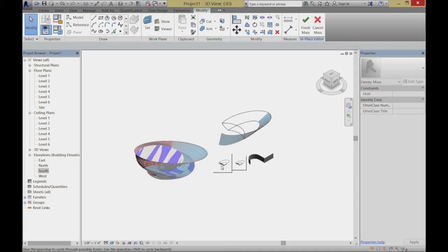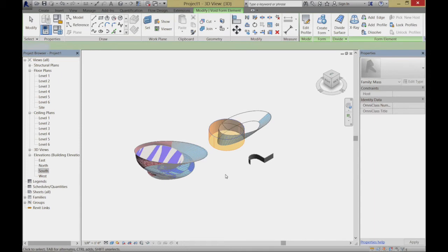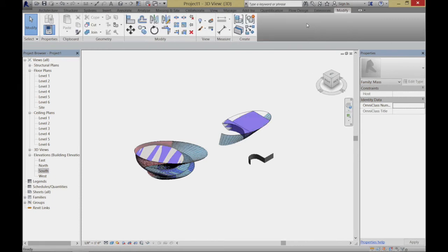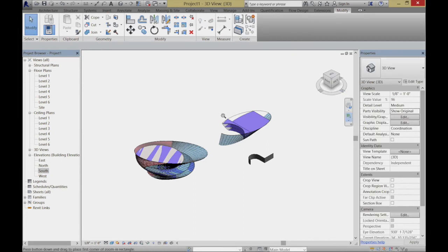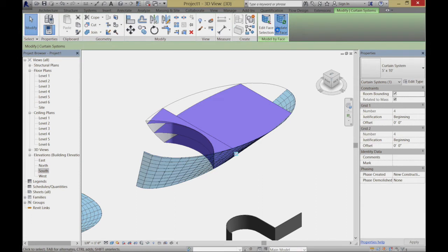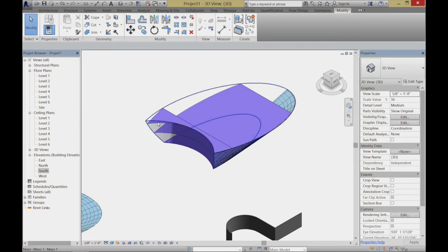It's going to ask us about this issue, which is kind of interesting: whether you want it to be a sphere, because it has a choice at this point. Okay, what's happening now is I've taken a void and carved away the backside of this dish. That's looking pretty good. Now, I've put that fantastic curtain wall on there, but it no longer reflects the surface, so what I've got to do is this little update to face. Okay, and then maybe I can put a different curtain wall on this face over here now.